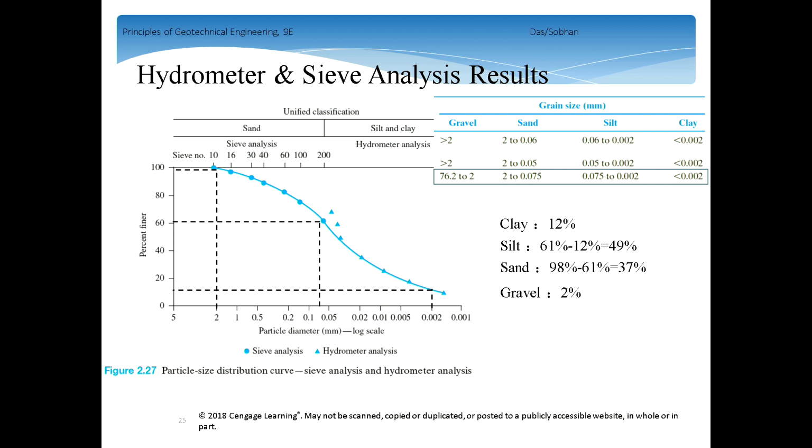You shake 15 minutes, that's actually enough for all those particles to pass the opening. If the particle is big enough to be retained on the sieve, even if you sieve for a very long time, because it's big, it can't pass the opening. But they may collide with each other and break.